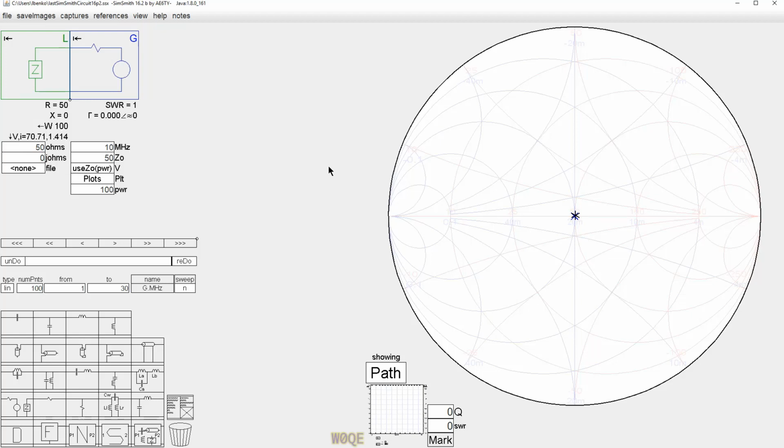Now, considering that a lot of solid state amplifiers have issues with turns ratios and stuff that are integer numbers, the generator might not be a 50 ohm output impedance. It might be a 45 ohm output impedance. And I've made some tests on some different transmitters, doing something called a load pull test. That's load PULL, where basically I would give the generator various impedances, say on a 2-to-1 SWR circle, or various impedances on a 1.5-to-1 SWR circle, and you would expect to see the same power delivered in all cases. And I can show that very quickly here.